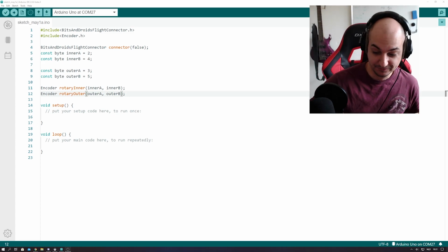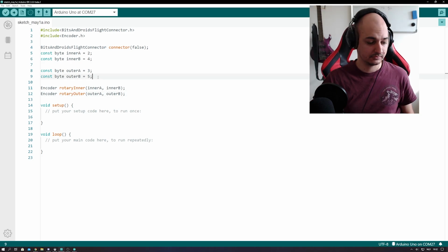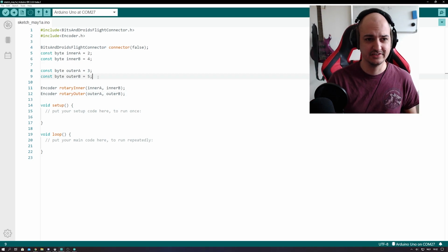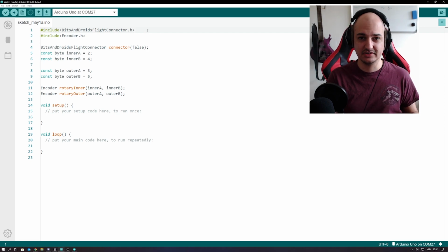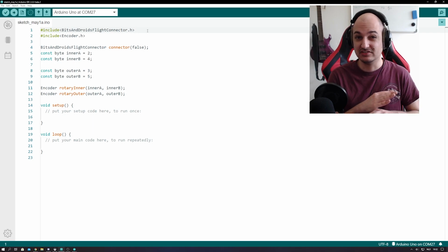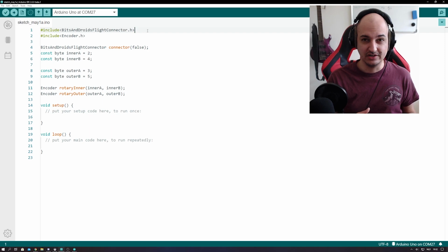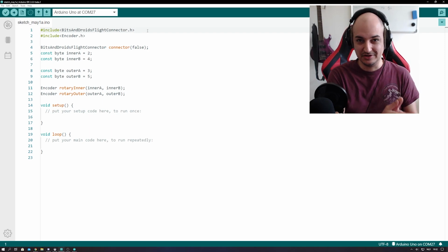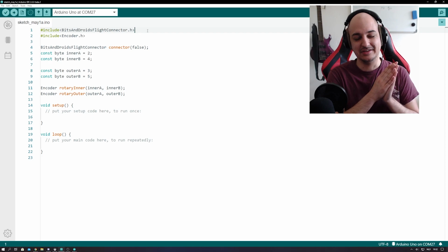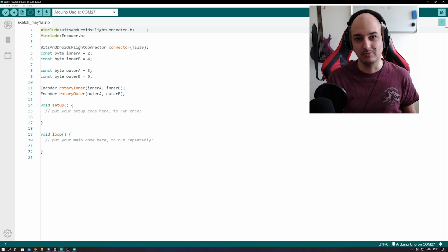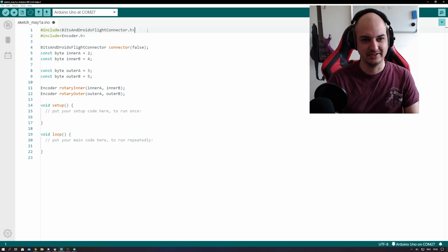Yes. So let's keep rolling. Now we also have our 2 screens, so I've got to include them. I'm using the TM1637 chip, and the chip is basically just a driver for 7-segment displays or LEDs in general. But why I'm using this is because it's dirt easy to program. The MAX7219 (whichever number, doesn't matter), the other one that's very, very popular, is also a good solution. It just takes a bit more code, and sometimes I like it to be quick and easy.